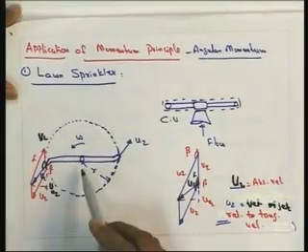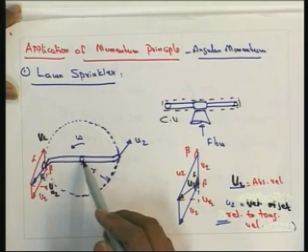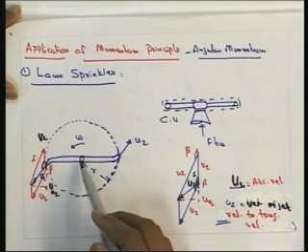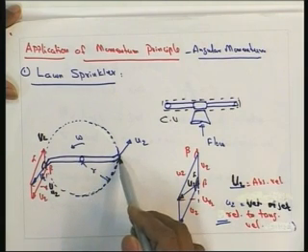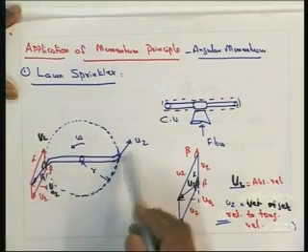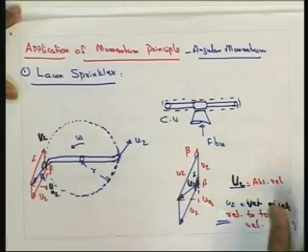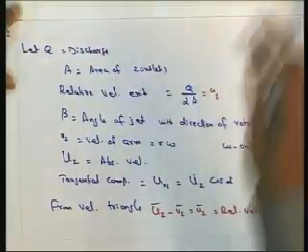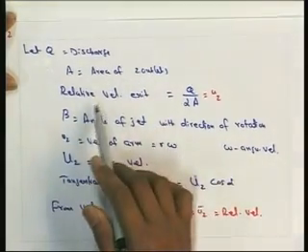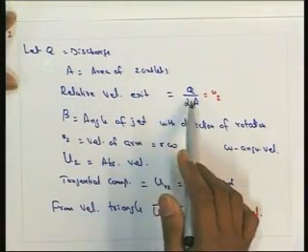So here the flow is, water is coming through the pipe here, with discharge Q, and that is divided into two nozzles, say A and B, and then it is going through the two outlets. So if A is the area of each outlet, the relative velocity at exit will be Q by 2A.